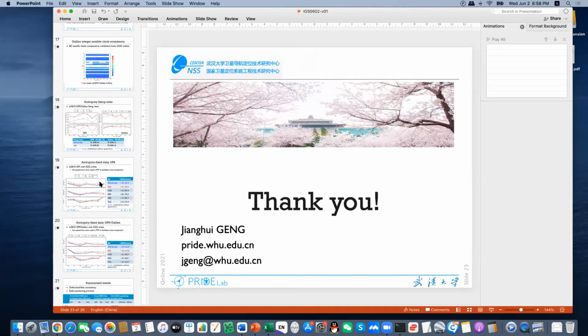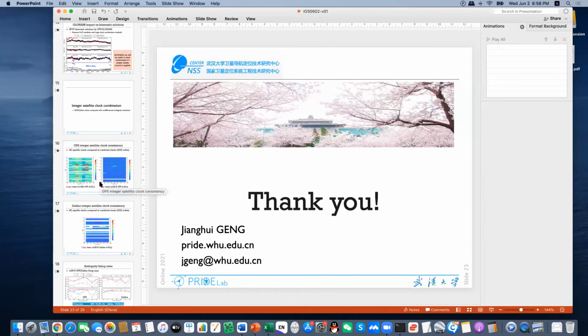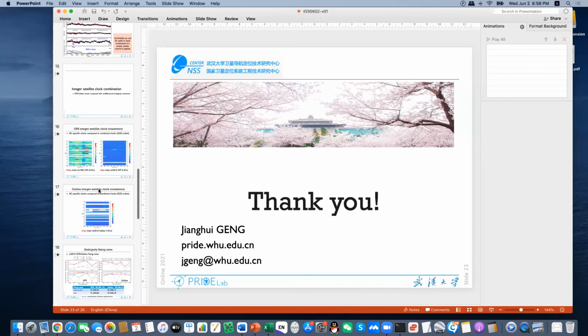I think I have a question. It's more of a general question in regards to PPP AR. So yes, we know that constraining the atmosphere improves the PPP initialization and solution convergence, especially in the first few minutes of processing. Is there any significant benefit in constraining the atmosphere in multi-frequency PPP for ITRF applications?